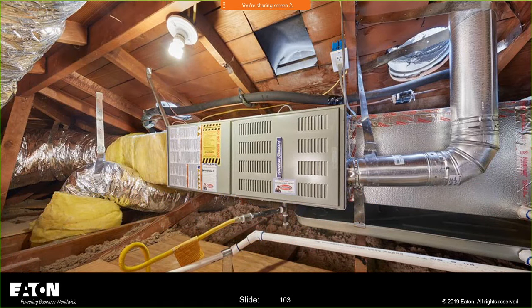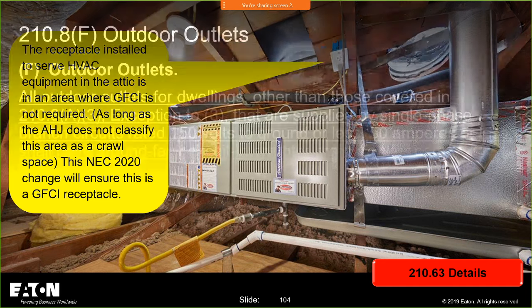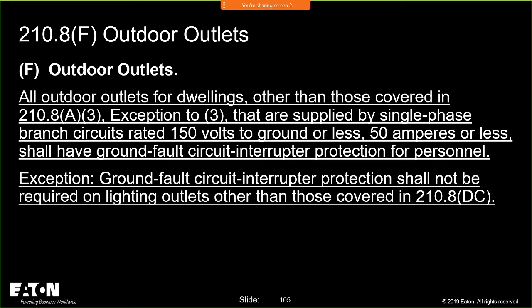Refresh yourself there. So here's an example of a receptacle that is servicing this equipment. If you call it a crawl space, okay, yeah, I could say that attic is a crawl space and I need the GFCI protection, and I probably would need GFCI protection on that light that's there too. But if it doesn't meet that definition of a crawl space, that receptacle in the attic would still require GFCI protection.